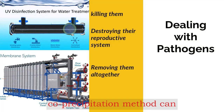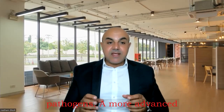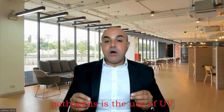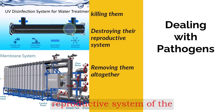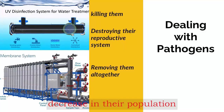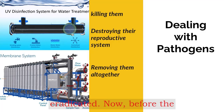Precipitation and co-precipitation methods can also remove a portion of the pathogens. A more advanced method for dealing with pathogens is the use of UV radiation, ultraviolet. UV light destroys the reproductive system of the pathogens, leading to a decrease in their population until it's ultimately eradicated.